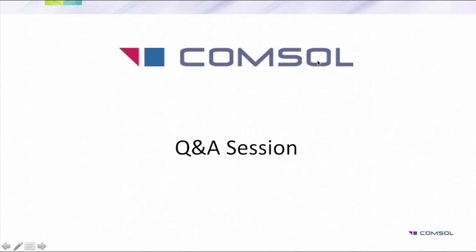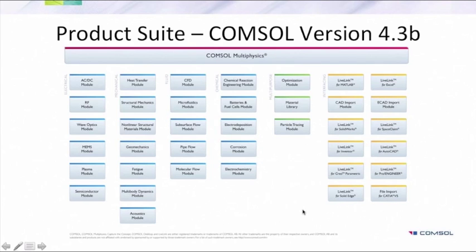So the first question I have, what kind of variables can be evaluated in COMSOL? Basically any variables which you can type an equation for. In structural mechanics, most of the variables depend on the displacements. Displacements are transferred into strains. Strains are transferred into stresses.